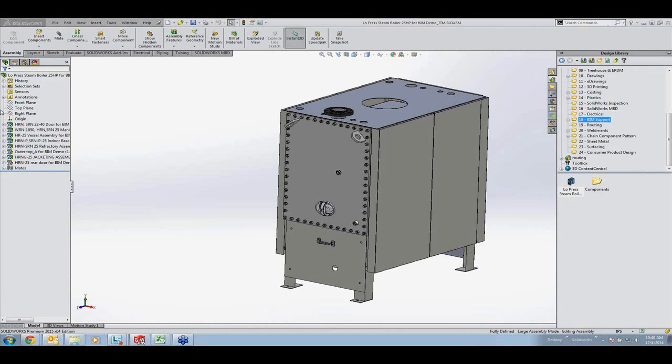And also, I could choose to select other components, say they're intellectual property that you don't want to get out there. You can go ahead and select individual components. This takes a second to hide everything here. What it's going to do is hide all those things that are 6% of the assembly size or smaller, which is most of the fasteners. Alrighty.